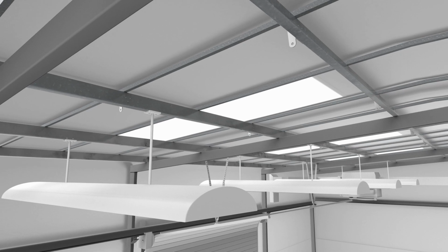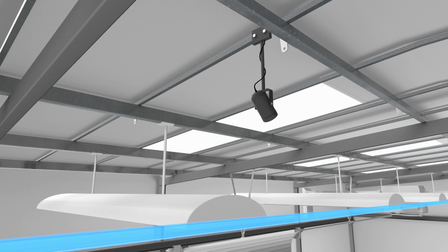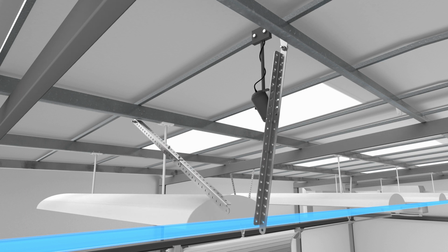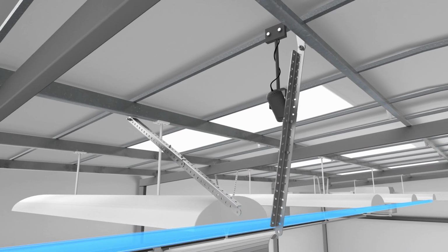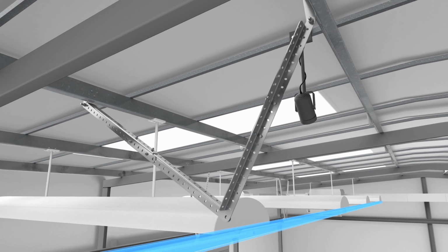Prior to installing the parallel purlin brackets, consideration must be given to the trajectory of the hanger link arms onto which the rigid rail will be secured. Where obstructions such as plant, equipment and services will prevent the hanger link arms from joining together to form the central fixing position for the rigid rail, repositioning of the Kee Track system or purlin brackets must be considered.